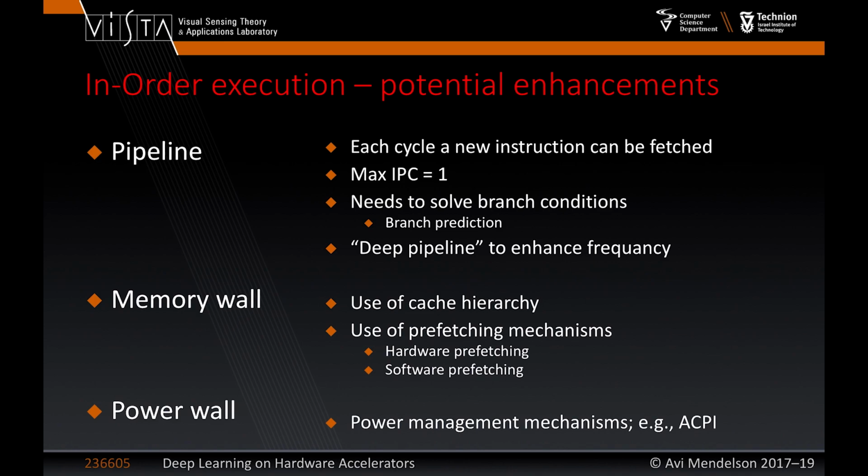So there are mechanisms that try to prevent it, which means that whenever you start to reach a dangerous temperature, the system doesn't allow you to continue, and it automatically starts to reduce the frequency. What does it mean to reduce the frequency? It means that you are slowing down your system, that you are losing performance. So if you try to do something very, very sophisticated, at the end of the day this mechanism slows you down. You cannot exceed some limit of performance because the system doesn't allow you to go beyond some thermal point.